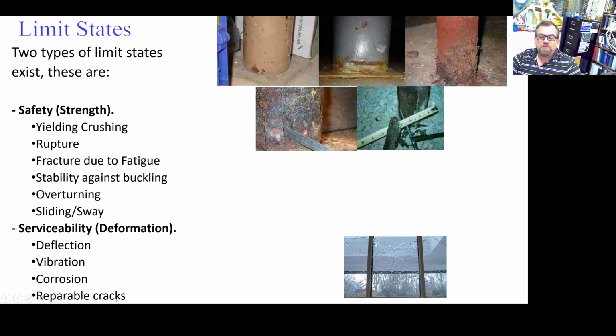Well, what type of crack is that? You have to pay attention not only to the thickness of the crack, but the location of the cracks. Usually 45-degree cracks at the supports mean that you have a problem with shear. What problem? I don't know, we have to study the case, but that's what happened. If you have longitudinal cracks on a girder, for example, that might have something to do with the longitudinal rebars, maybe because they are corroded internally. I don't know that either. We'll have to study, but we have to pay attention.